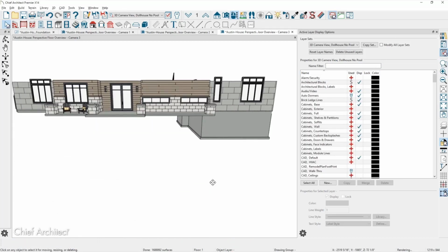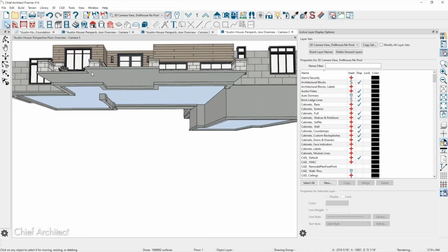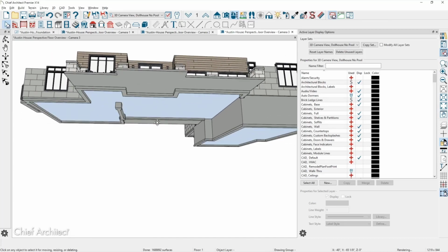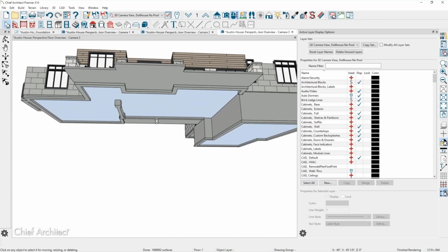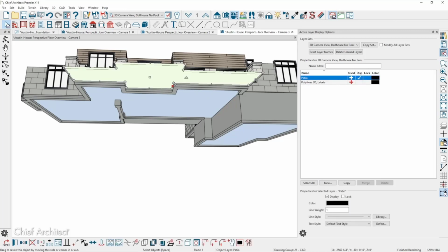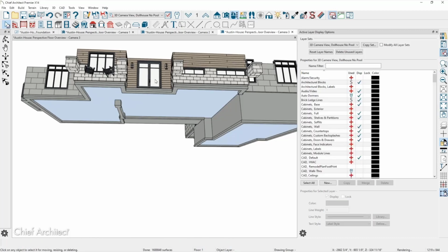And this is supportive. This actually has no structure, so you can see I just drew that as a separate slab. And then in my cross sections, I don't see that 36-inch peripheral beam because my roof supports with columns or something like that. It comes on that slab, and that slab needs to have those grade beams. So essentially that waffle slab extends to the extent of the edges of the slab that you have created. Okay, so the foundation would need to go out and basically remove this one that I drew, and your foundation needs to come out.